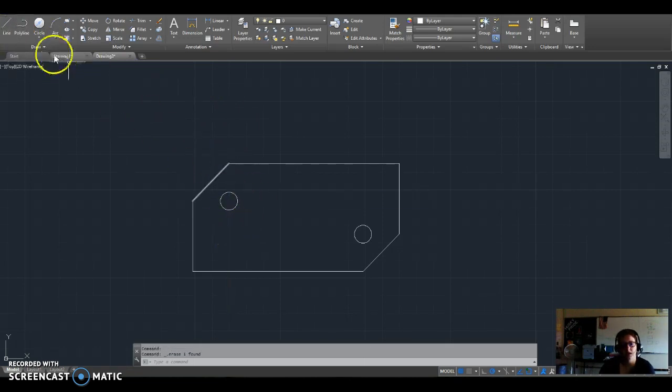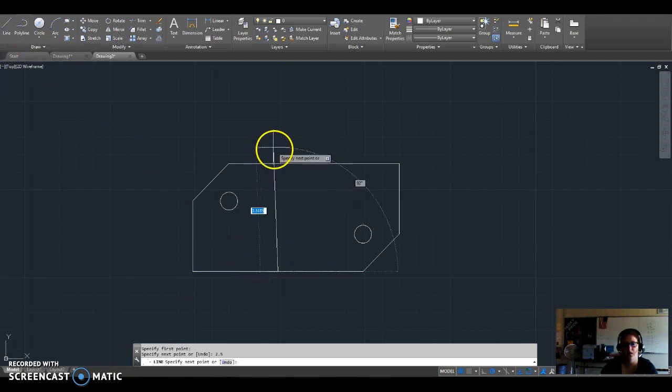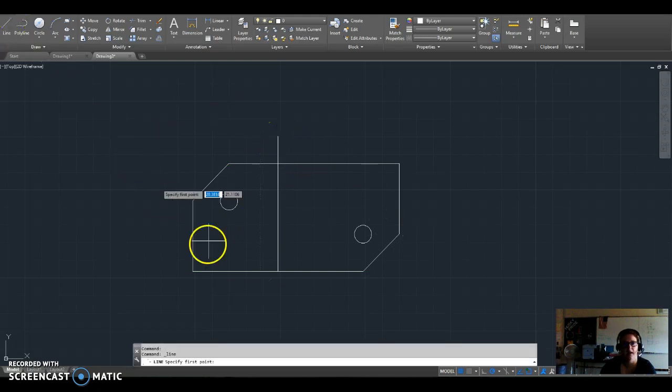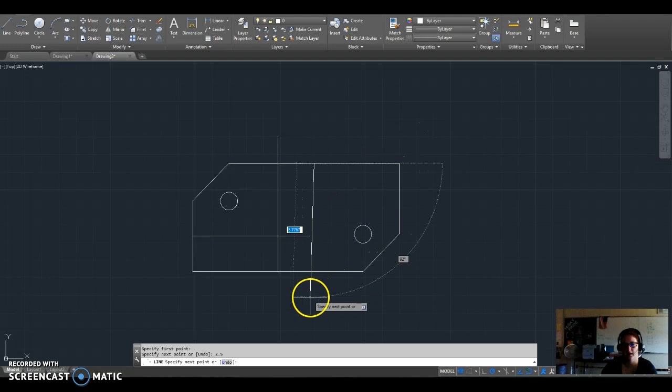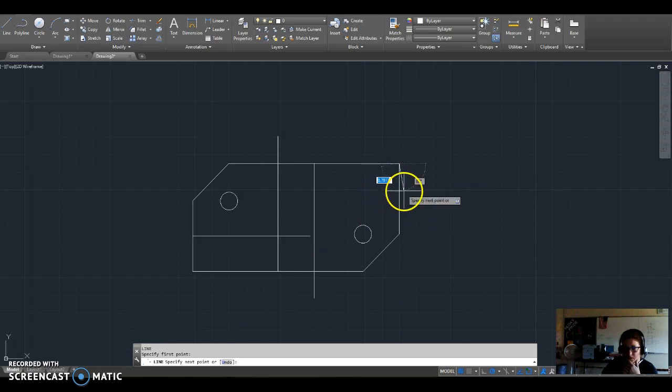For the big circles, the dimensions are a little bit harder, so I recommend you just draw extra lines, since it's not 2 over. It's 2.5 over, so I created my line, 2.5, enter, I go up 90 degrees, and then I go line down here, it's 1 up, and I come over, and then I do that again up here, create my line, 2.5, then I come down, and then I come over here, I go 1, and then I come over.